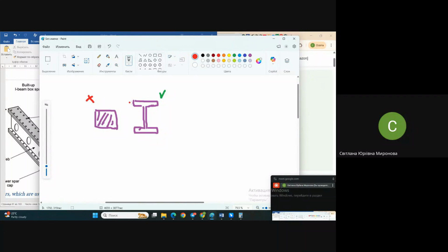That one would, with the same area, seems like it's impossible. Right? For tension, they will be quite the same. For tension, sigma breakpoint will be the same in this cross section and this cross section. But when it comes to both tension and compression, meaning bending moment, that one will be more effective than a simple one like this. It will be lighter in weight.